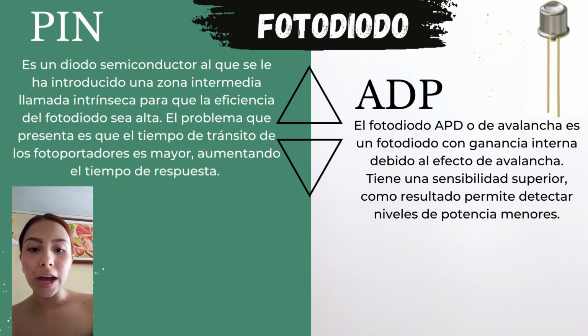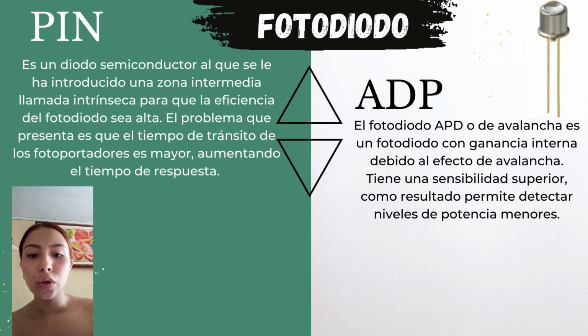There are two types of photodiodes, which are the PIN and the APD. The PIN has a semiconductor diode to which an intermediate zone called intrinsic has been introduced so that the efficiency of the photodiode is high. The problem it presents is that the transit time of the photocarriers is longer, increasing the response time. And the APD, or avalanche photodiode, is a photodiode with internal gain due to the avalanche effect. It has superior sensitivity. As a result, it allows detection of lower power levels.